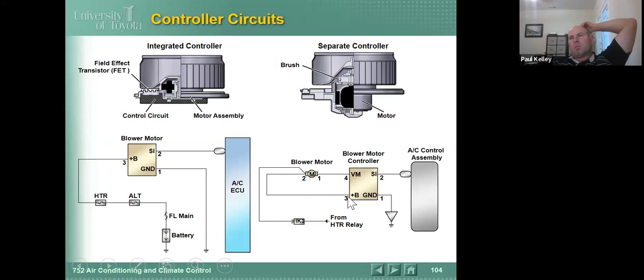So 12 volts is going to be constant in a lot of cases, but the ground will be pulsed on and off. And the thing is that if you figure that ECU, let's call it the ECU, just for Universal Electronic Control Unit, ECUs don't play games with big amps, okay? Big amperage and small circuits don't play well.